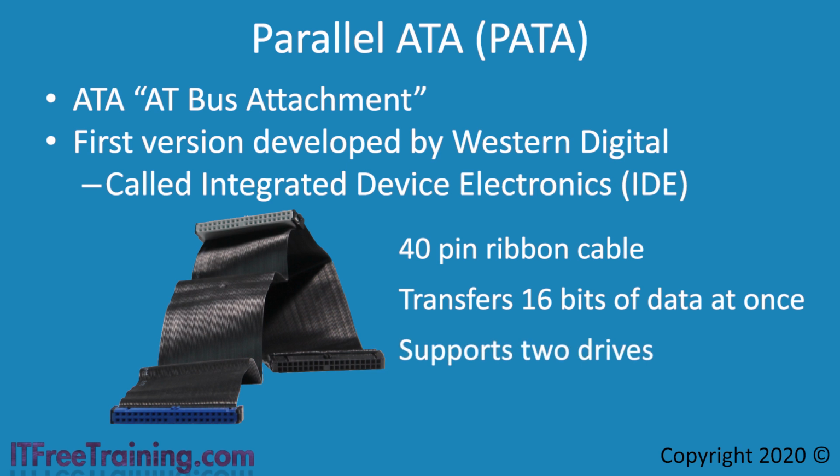The standard supports 2 drives. This is why there are 3 connections on the cable. One end is plugged directly into the motherboard. The other 2 connections are plugged into the storage devices. It does not matter which connector gets plugged into the motherboard, but you will generally find that there is a larger gap between the middle connector and the end connectors on one side. Generally, you would plug this end in the motherboard to give you more cable length to attach your devices to. The name IDE was quite popular at the time, so you will often hear the cable referred to as an IDE cable, or the plugs on the motherboard referred to as IDE.